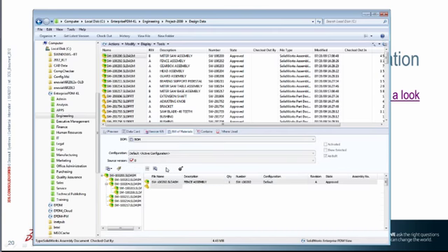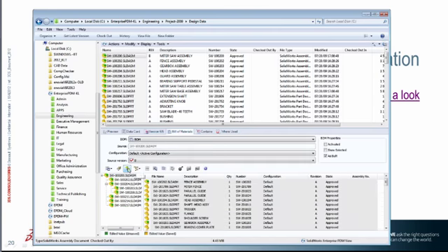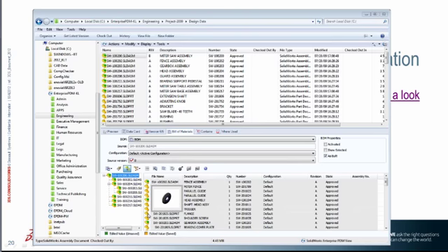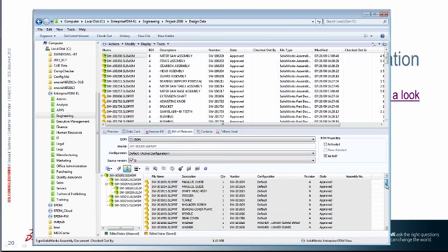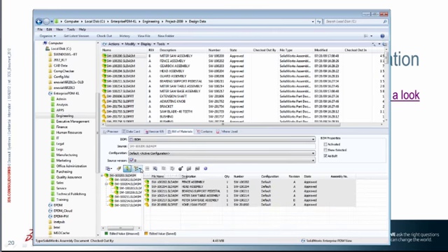All right. So looking at some of the other controls here, I can show this tree to the left side, which shows all the subassemblies, which I can collapse or expand. If I hover over these files, I get a nice little thumbnail that gives me an idea what that part is, what it looks like. I can show this BOM in an indented list, or I can see a flattened BOM, which takes out all the subassemblies and just shows me parts and rolls up all the quantities. So if the part was used once in 4 different assemblies, it would show quantity 4 here. And then I can also look at a top level, which just shows the files that are associated right at the top level of this particular assembly.